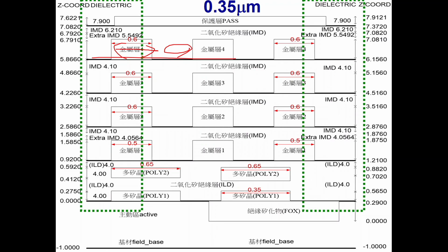It means process evolution happens almost entirely for horizontal parameters. The width of the metal line is horizontal, right? The spacing for metal lines on the same layer is also horizontal spacing. And how about the vertical spacing between different metal layers? Sorry, not much evolution happens vertically. Evolution usually happens horizontally. Please keep this in mind. That is really important for all the processes. And also that is some kind of limitation by nature.